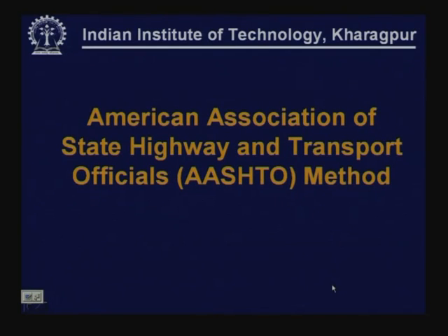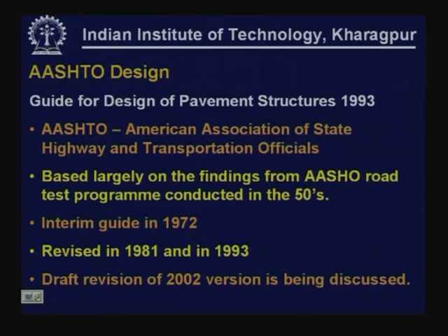We will next deal with the American Association of State Highway and Transport Officials design method of designing concrete pavements. We are referring to the Guide for Design of Pavement Structures 1993. As discussed in the case of design of flexible pavements using AASHTO design procedure, this design procedure is also based extensively on the findings from AASHTO road test, which were conducted in the 1950s.